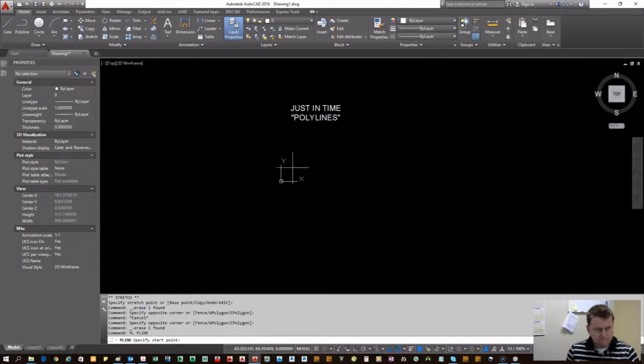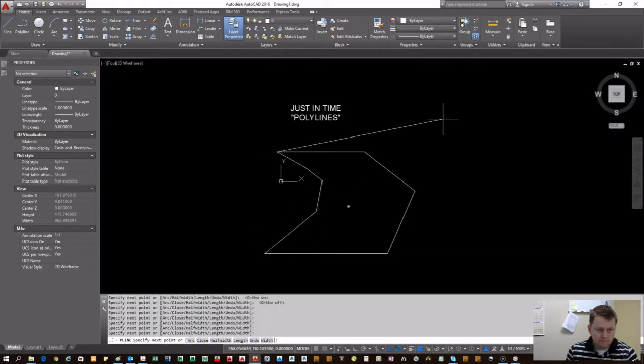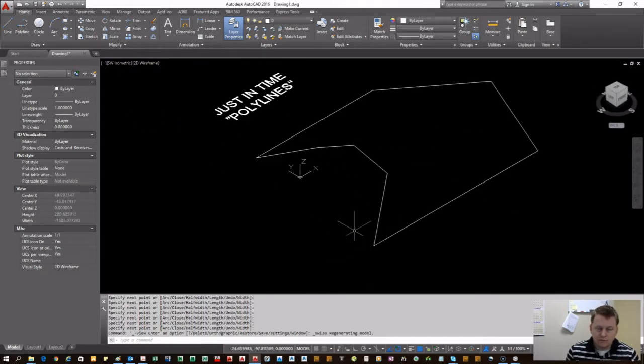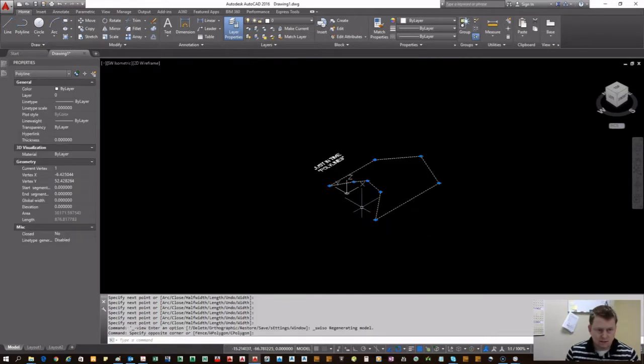One more feature. This will be our last thing that we cover. It is that when you have a unique footprint, and this is going into something a little bit further down the line for most people, I am now in a 3D perspective. So I've changed to my isometric perspective, which means I now have a z-axis, so I have an elevation besides just my northing and easting.